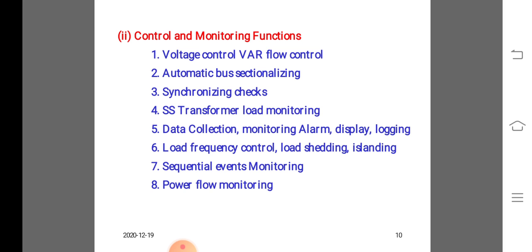communication cannot be made through open disconnects. When the transmission line is outaged, often this is precisely the time when the communication signal is needed most. In addition, PLC is susceptible to line noise and requires careful signal to noise ratio analysis. Most PLC is strictly analog, although digital PLC has become available from a few suppliers during the last few years.